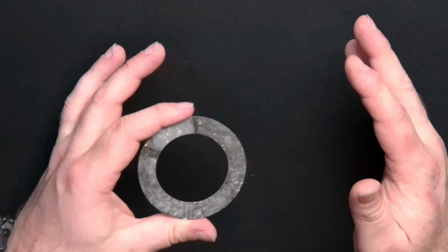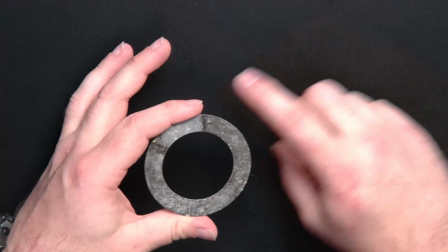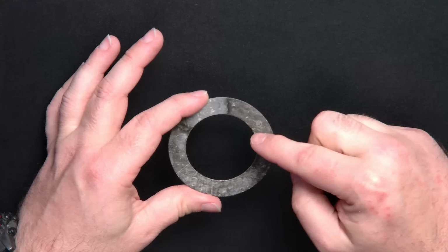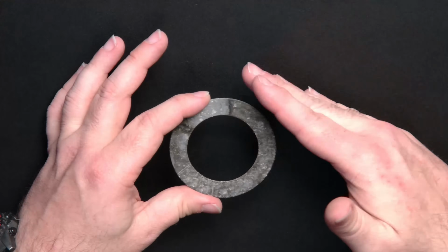They made them bigger, and if it was for a really big pipe, a lot of times you'd have to use a sheet gasket and cut it out. But this is what an asbestos gasket would look like. And you can see the white fibers, that's chrysotile asbestos. I'm not particularly worried about the health concerns of being around this, because I'm not grinding on it or cutting it or slashing it or doing anything that could really release the fibers and get them in the air.